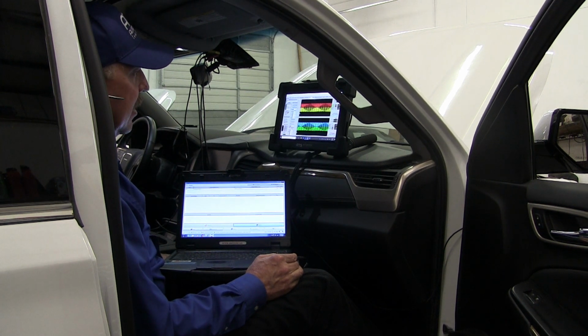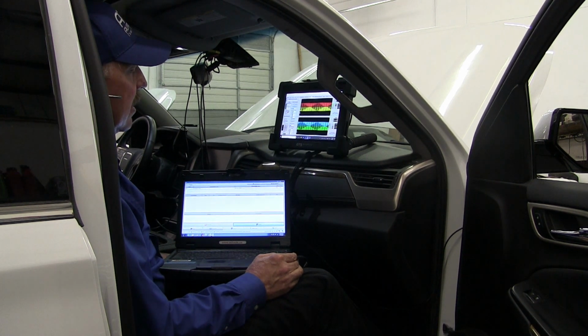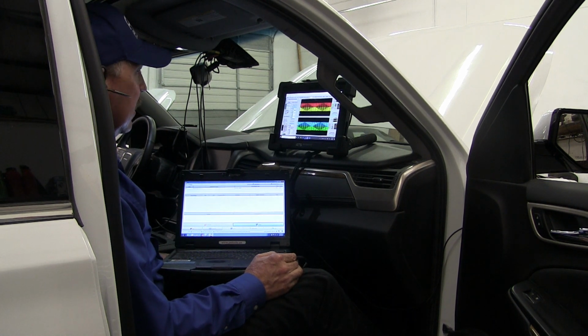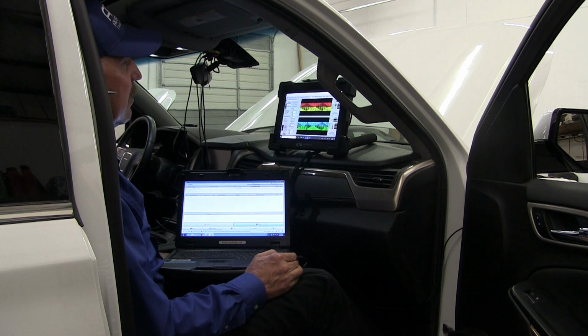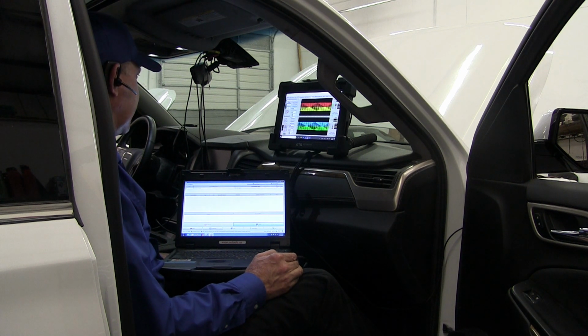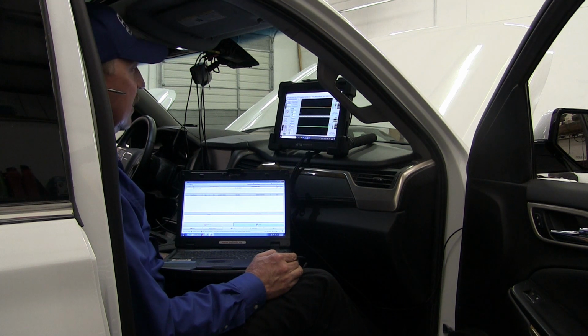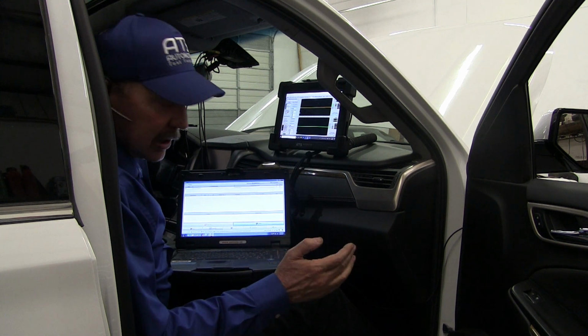So that's sleep mode right there for this type of car. Some of them drop below 1.7. Usually I expect 1.4 volts for the bias voltage that's on here, but this car has a different shutdown, and it does stay at the 2.5 in divisions. So now we've got this car asleep.